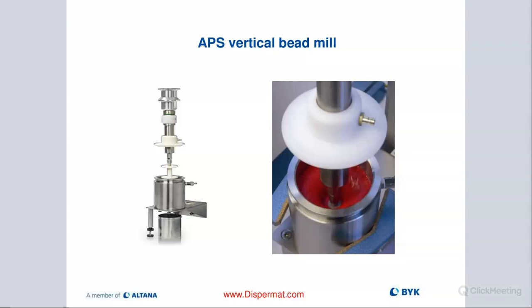And then you basically push and you add your beads. You can add 100% bead loading. So if I have, let's say, 500 milliliters of slurry, I can add 500 milliliters of beads, which is really good. I have a lot of beads then in my container, helping us with the breakup of our particle binding forces.